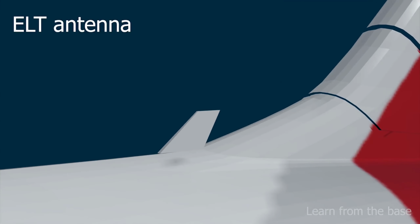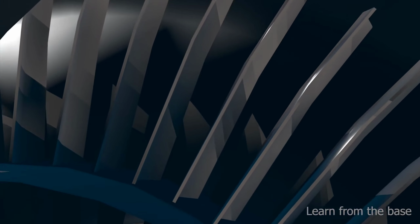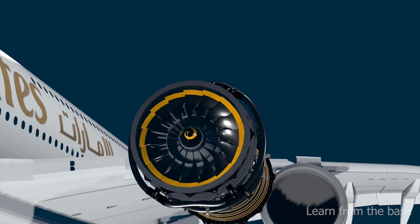Let's see the main part of the aircraft, the engine. Each engine generates 40.5 tons of thrust, at more than about 75,000 horsepower. The total thrust produced by the aircraft is 165 tons. The fan operates at nearly 3,000 RPM with a tip speed of 1.5 times the speed of sound. Fuel cost for flying the aircraft is approximately $29,000 per hour. The engine's titanium fan blades suck in over 1.25 tons of air every second.